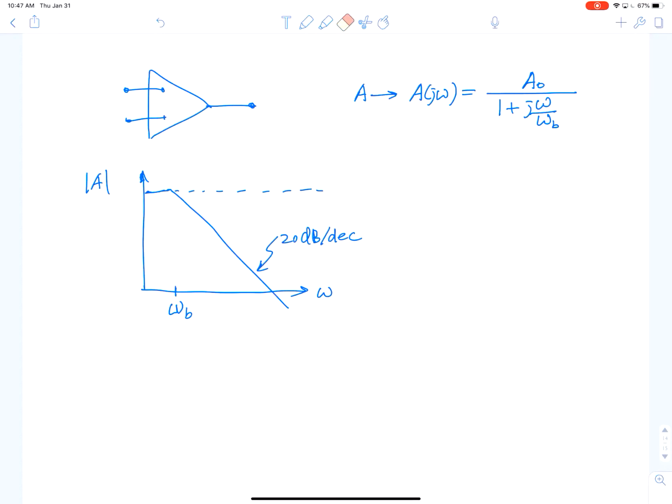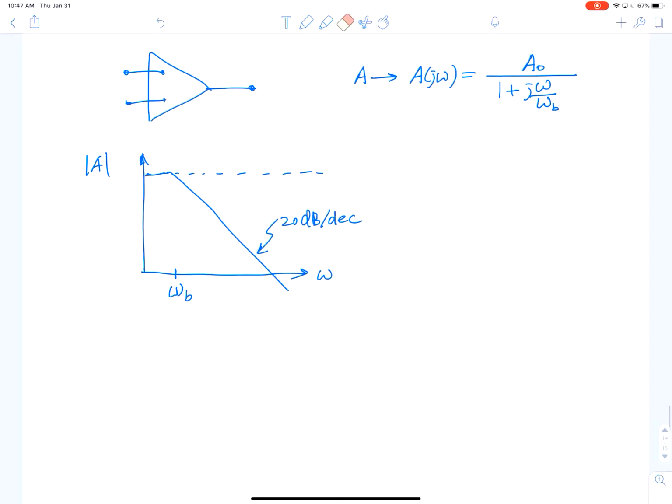We did go over what determines omega B. What is omega B? We kind of gave you a preview. Your op-amp really consists of two parts. It's like we are sawing it apart, but realistically, if you are an op-amp designer, you literally design the input stage called the operational transconductance amplifier, OTA.